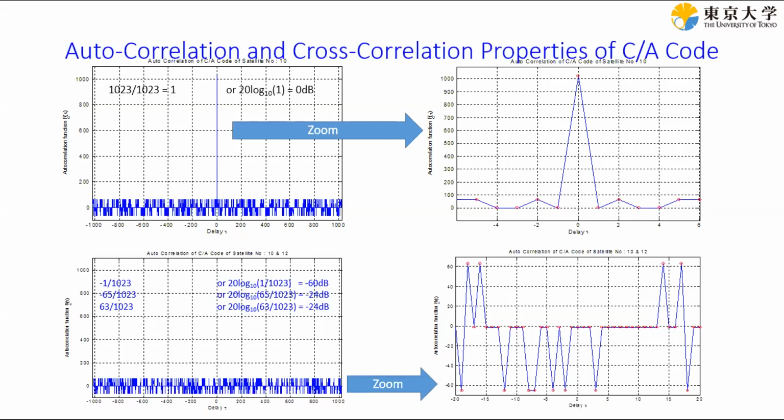That means the signal is coming from the satellite, and now you are trying to read that signal in your receiver. So the way the receiver works is that the receiver also generates the same signal. If you are going to track PRN code 1 or satellite number 1, you have to generate a replica of the PRN code 1 in your receiver.